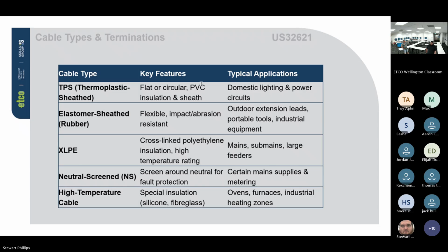Cool. So when we terminate our mains, earth or main neutral, I guess you would technically have main, even your main phase, you don't have to do that. So what is the requirement for connecting your main earth and neutral? MEN link, well, we need to have one in the installation. Double nut. 2 nuts on bar, yep.